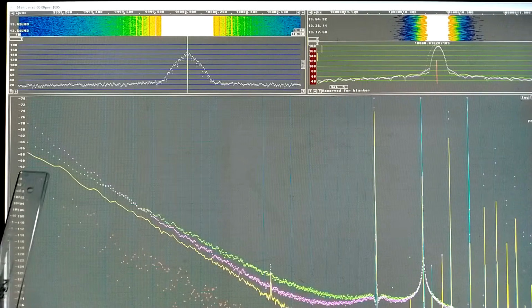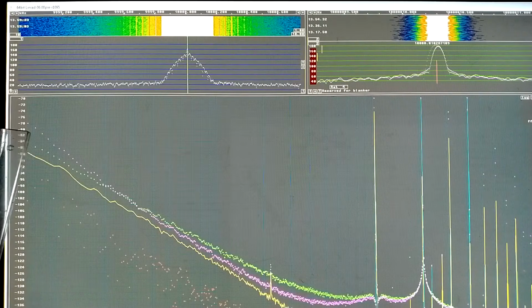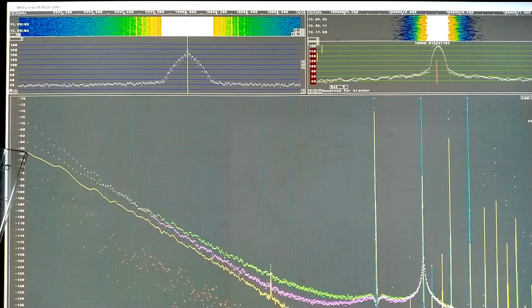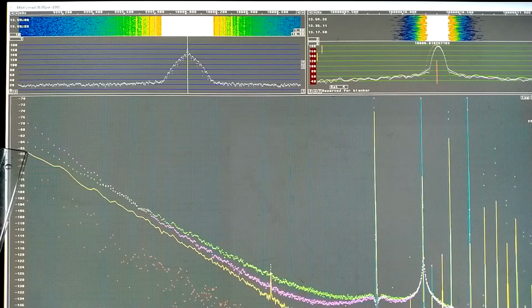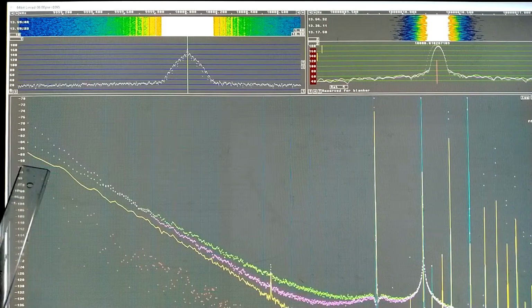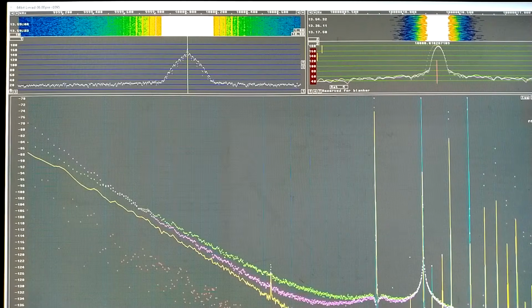But at 0.1 Hz, the channel 2 oscillator is not good at all, and even closer to the carrier it drifts away and becomes 6 decibels more noisy than the Wenzel oscillator, which is 3 decibels above the yellow trace, which means the level is the same for the Wenzel and for the box I'm experimenting with, and the level is at 0.07 Hertz minus 88 dBc per Hertz.